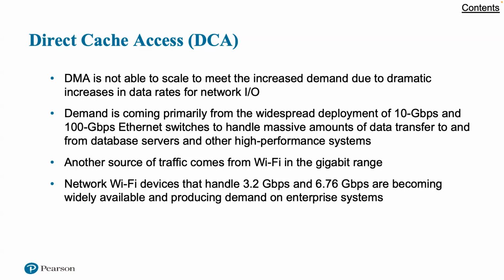To begin, we describe the way in which contemporary multi-core systems use on-chip shared cache to enhance DMA performance. This approach involves enabling the DMA function to have direct access to the next level cache.